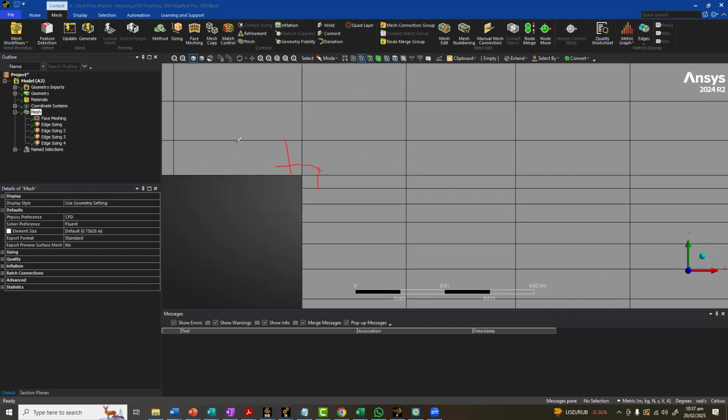Clear? So it means that now we have to change the biasing here so that the cells can come close to the corner here. Similarly, here as well. So the biasing on the bottom side is okay. Here is okay. But here and here, this is not okay. Okay. So now I will play with biasing here.